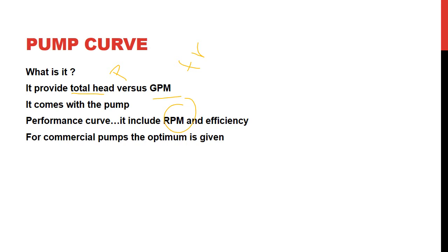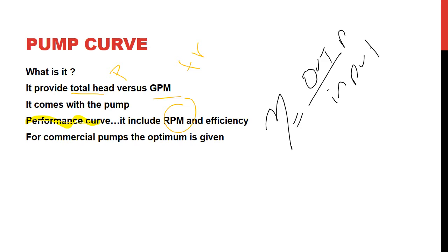So there is something called the performance curve. This is the performance curve, an experiment that's done on the pump when they manufacture it, to tell you the efficiency of that pump at a certain RPM. So it does vary. You cannot just increase the motor speed to have the pump perform differently, because that will affect the efficiency. And we said before, what is efficiency? Hopefully somebody will shout it out right now. Efficiency is output over input. So what is my input here? Electricity.